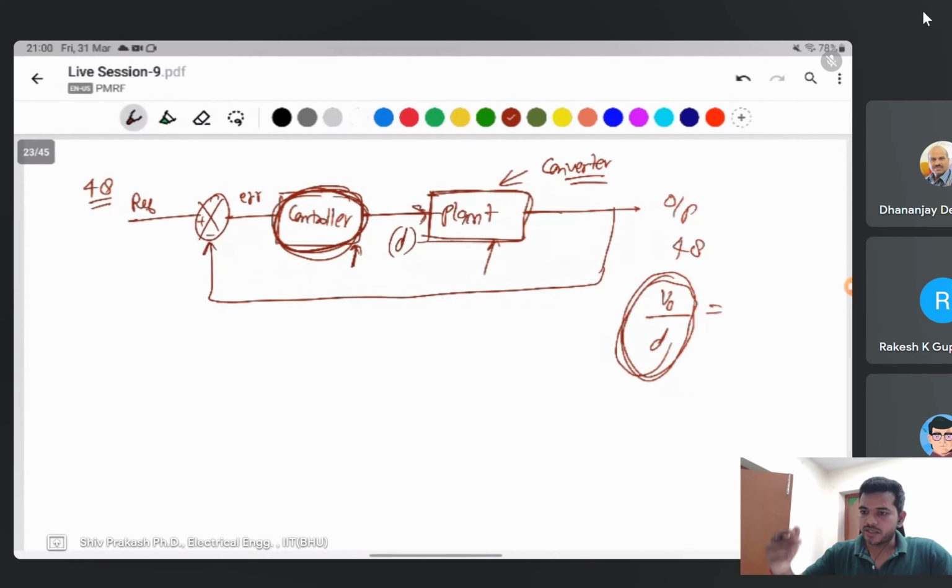In the ideal case, with a constant output voltage and constant input voltage, the inductor current will be constant. But in practical cases, the output voltage is not constant, and ripple current occurs. The ripple is not purely linear in those cases. Then you can convert it to linear by taking a small amount of variation.